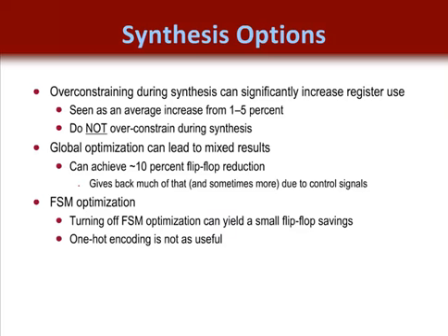It is also important to determine whether your finite state machine is part of a timing critical path. Often they are. If so, you may have little choice but to use one-hot encoding. But be an engineer and evaluate the encoding yourself. Note that over time, this is something synthesis tools will learn from and will improve upon.